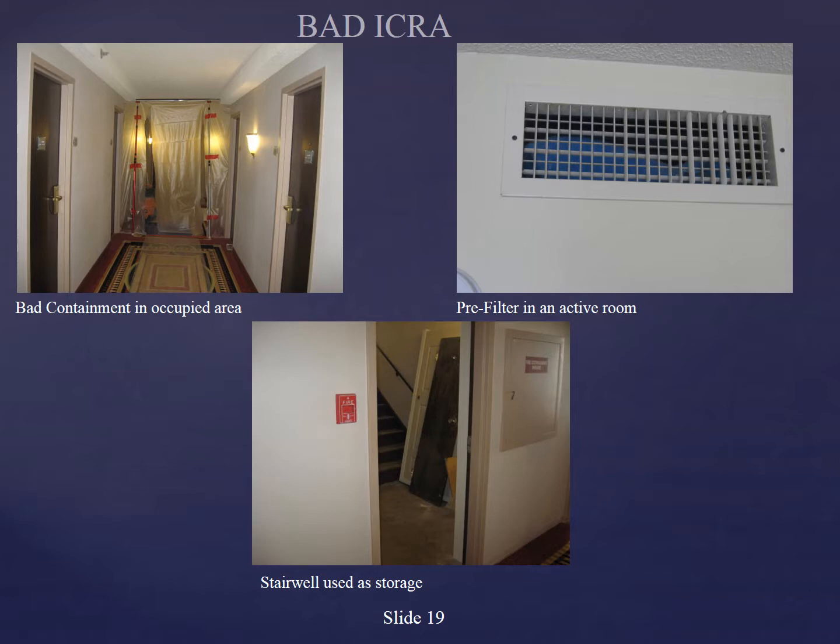And then down below, there's a stairwell used as storage. Again, it's just too common a practice to use what's available to you. Because stairwells sometimes have a nice, great big landing space, and it seems like there is space to put stuff, it's real common for people to just say, hey, go put it there. And you can even see in that space where the storage equipment is that someone coming down those steps in an emergency, or if you had a bunch of people coming out, this is going to cause one bad situation.